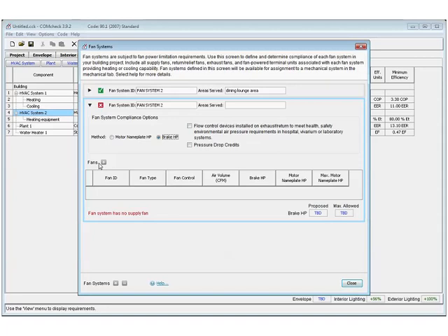But we'll just go ahead and enter a fan real quickly here and say supply. Let's put in single zone again. Let's even put in the same CFM that I had. And we'll put the brake horsepower at 3 and the motor nameplate at 2.